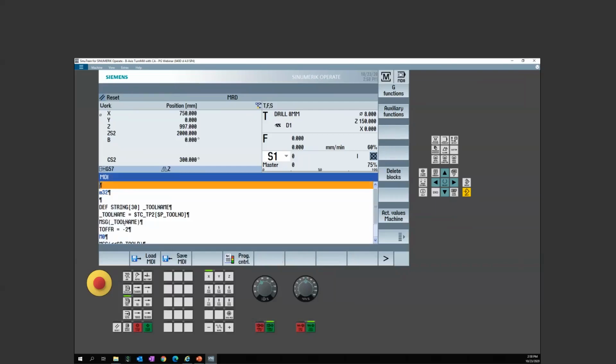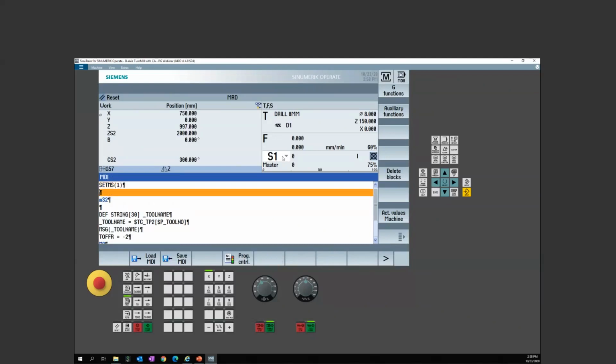So if you take a look here, let's say for argument's sake, I want to fire up spindle 1. So I can absolutely tell it, and I'm going to be in caps, set ms number 1, and yes, I can say spindle 1 equals some RPM. M code for spindle 1 will equal a 3 for clockwise. So this would fire up the spindle at, and of course my override is low, get it to 100%, so 1000 RPM.